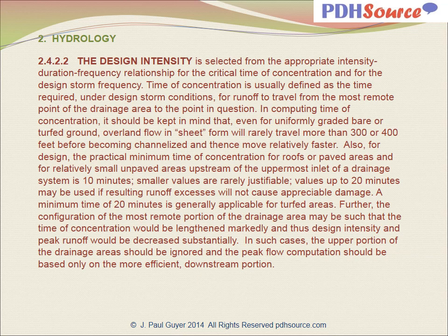Smaller values are rarely justifiable. Values up to 20 minutes may be used if resulting runoff excesses will not cause appreciable damage. A minimum time of 20 minutes is generally applicable for turfed areas.